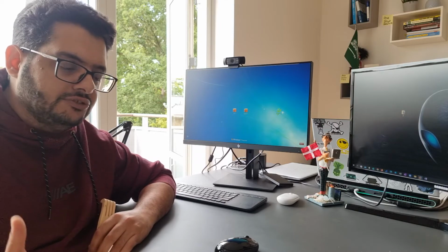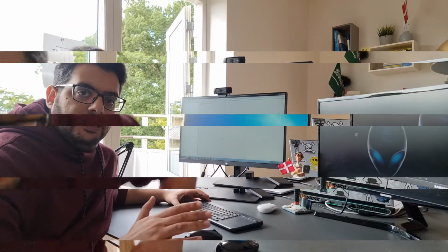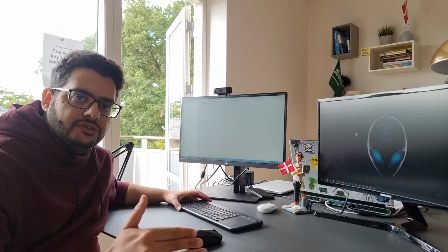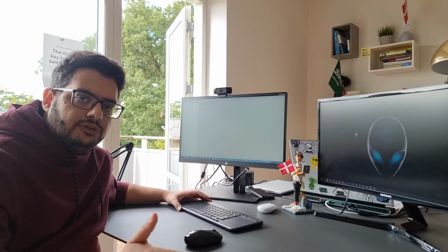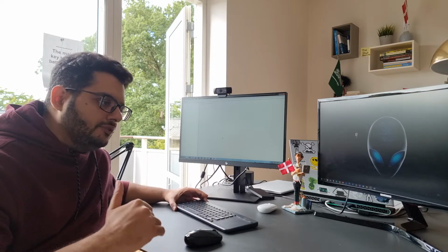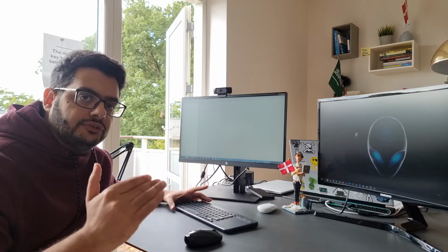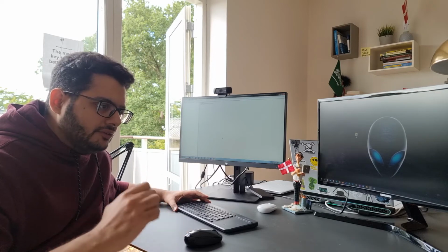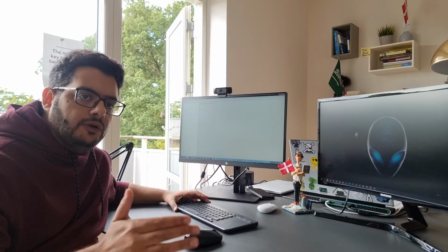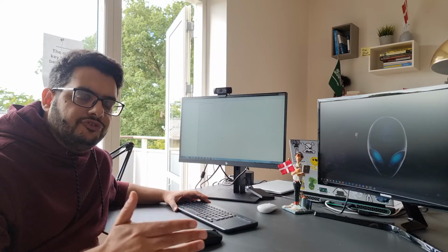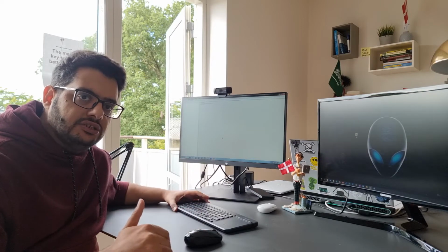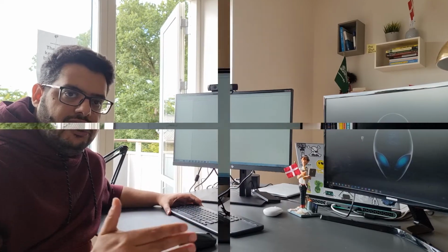And you really need to consider this when you assess any engineering workstation. If a hacker can maintain access to your industrial control system facilities via an engineering workstation, then we are talking about a major risk. The attacker could use all the available tools, software, and applications against your industrial control system.